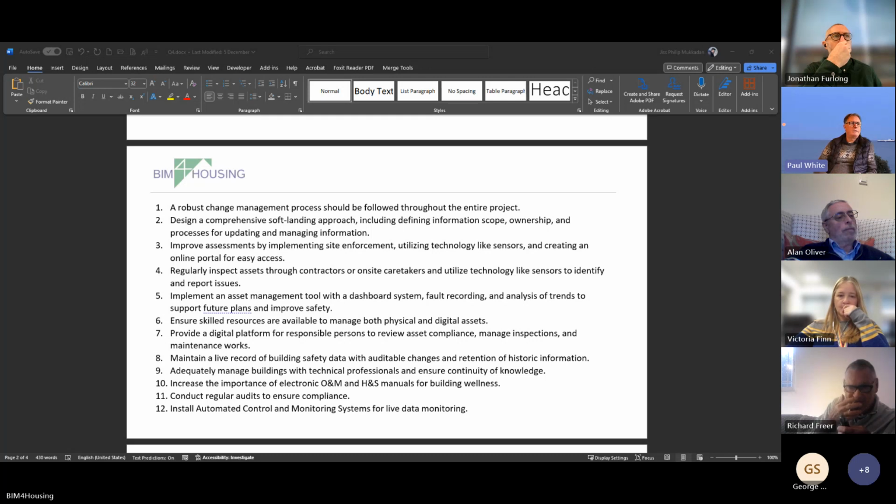But also, in terms of this system of your live safety building data, you've got a fire alarm inspection. You've got to keep all the records. You're now starting to realise you're going to have fire door inspections. You've got to keep all the records. And in keeping all these records, you're building up a whole record of, if you do nothing, exactly how long you've been doing nothing for. And then we add into that smoke control systems. We add into it ventilation systems with fire resisting duct. And we add into that fire dampers.